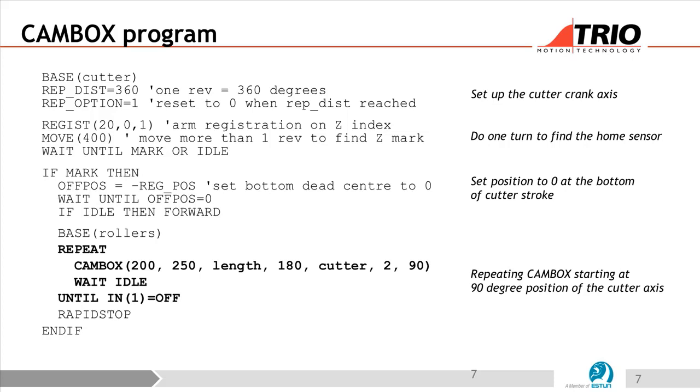So I can see you're quite keen on the possibility of using cams and putting your own things in. Yeah. If you do it on a larger scale, you just got to remember that in between each point it's a linear interpolation. So if you have 2 points and it takes you 2 seconds to go between them, it will follow them in a straight line.